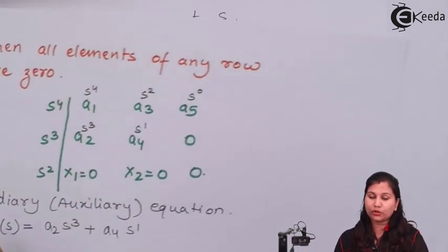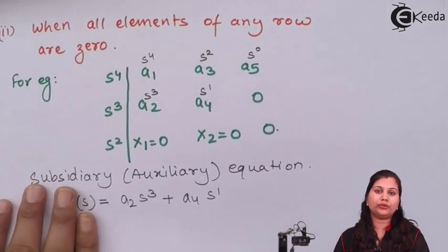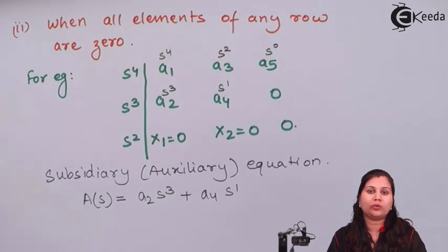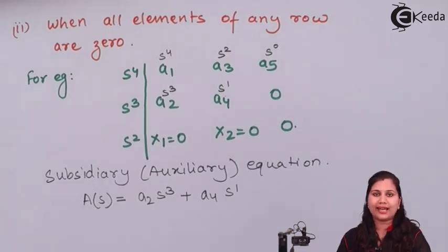So in this video we have studied the Routh stability criteria, that how we can make a comment about the stability of a control system, whether it is stable or not stable, using the Routh Hurwitz criteria. You have to just use the characteristic equation, then form the Routh array, and then check the number of sign changes in the first column of the Routh array.